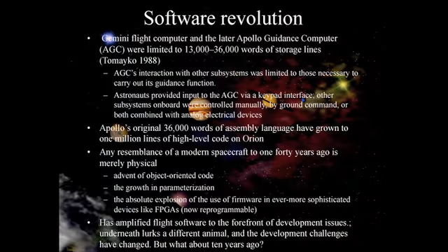There's a couple of things that bother me. One is that object-oriented code did create an inflation of its own, but secondly is this growth in parameterization, which is all the data elements that used to be embedded in the small groups of code that we had. You remember the 1024 RAM that you were allowed to have, KRAM. Now you've got huge lines of code. We've got hundreds of thousands of parameters now, data elements that have been pulled out of the code and they actually exist in files that we have to uplink to the spacecraft, which can radically change the behavior of the code. In fact, it's like writing code all over again.